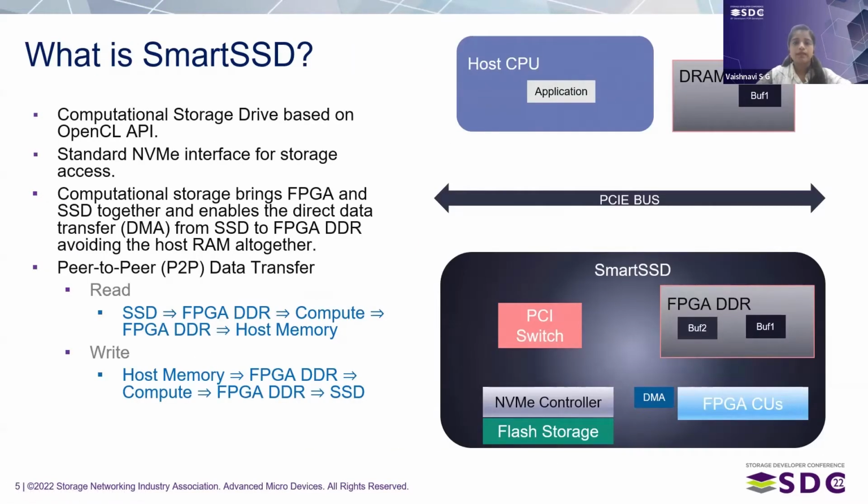We have used SmartSSD for the accelerator and storage. SmartSSD is a computational storage drive in U.2 form factor with NVMe interface for storage access and FPGA as accelerator. I'm sure you all know what FPGAs are, but for those who don't, FPGAs are configurable architectures that can be optimized for any workload in milliseconds by simply uploading a bit stream.